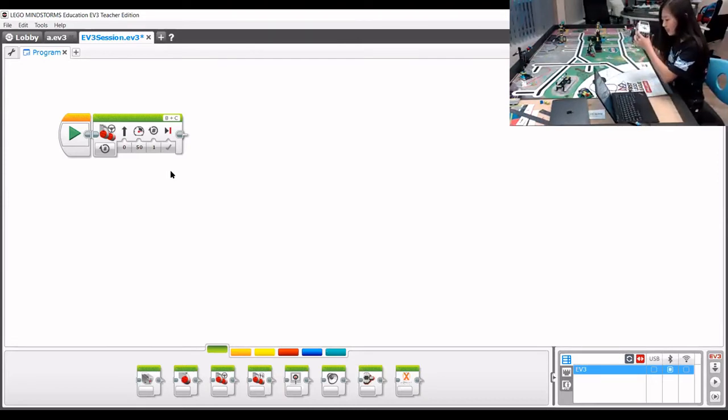The robot will start in this area, which is the base, and you guys have to find a good alignment spot to start the robot every time. This is really important because where the robot starts running its program has to be consistent every time in order for the code to be consistent. In this case, the robot is aligned with the first logo, because there's a box around it.